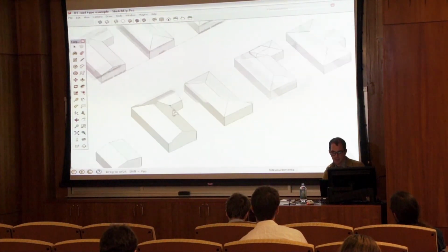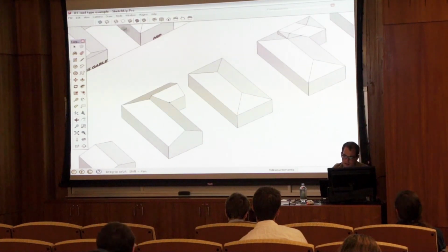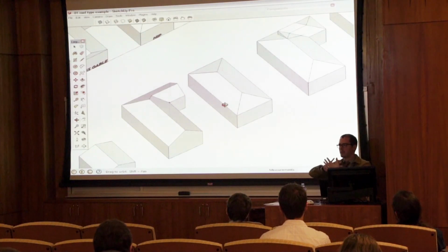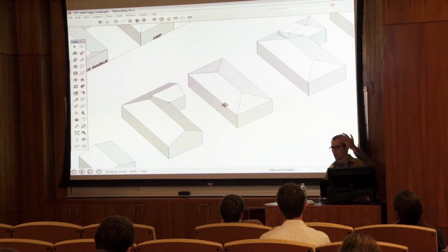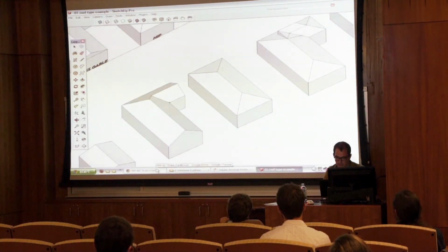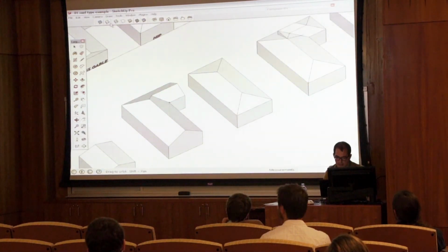New little feature that's been brought in to SketchUp 8 is this little icon here. So we use the vanishing points. This one to the right of it is called back edges. And for me, I like this. It basically does a dotted line of the geometry that's back or hidden. And in some renderings, what I'll do is in Photoshop, I'll have my textures, I'll have my shadows, I'll render that, but then I'll put a multiply of just the hidden lines and then a multiply of the back edges on top of that to basically create a composition of the model. And it just adds another level of detail, and you get to see the geometry of the file. And that's in back edges.